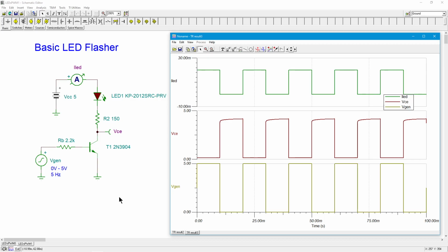Right? So you have a sensor out there, a sound sensor, a light sensor, a temperature sensor, whatever it is. And you can use that with the microcontroller to control what the duty cycle is. And now the brightness corresponds to this other variable. Okay? That's kind of interesting. Like I said, this is just a simplified thing that you can very quickly hook up